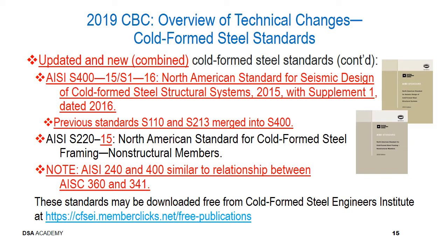It's worth noting that the AISI S240 and S400 are similar in their relationship to that seen between AISC 360 and 341. These standards may be downloaded for free from the Cold-Formed Steel Engineers Institute at the link provided.